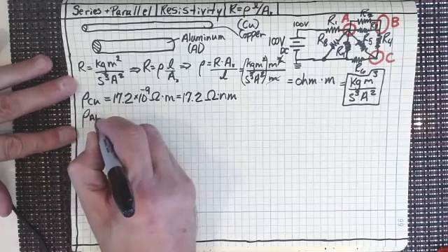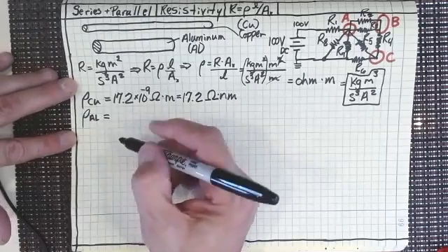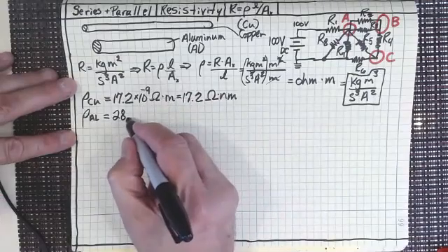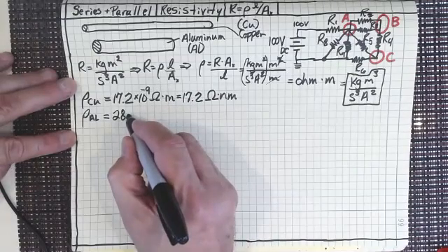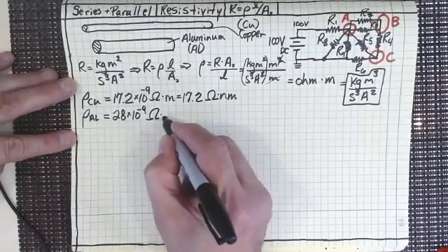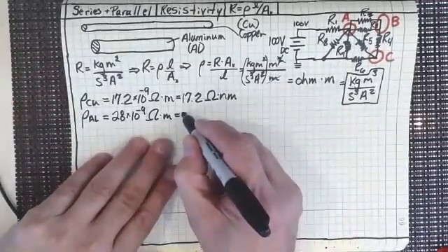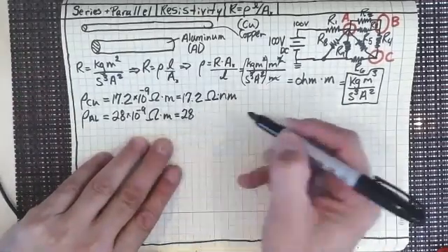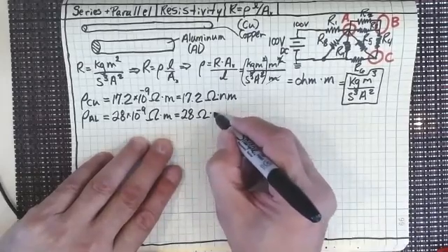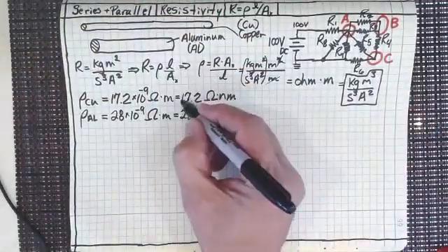Now, the other main conductor that we've got, and they point this out in the book too, and this is something I wanted to point out to you, is aluminum. And aluminum in the book, they also have a little bit high. I think of it as 27 ohm nanometers, but they have 28 times 10 to the minus 9 ohm meters, right? If I want to write that in ohm nanometers, it'd be 28 ohm nanometers. So those are the two, and look at the difference between the two.